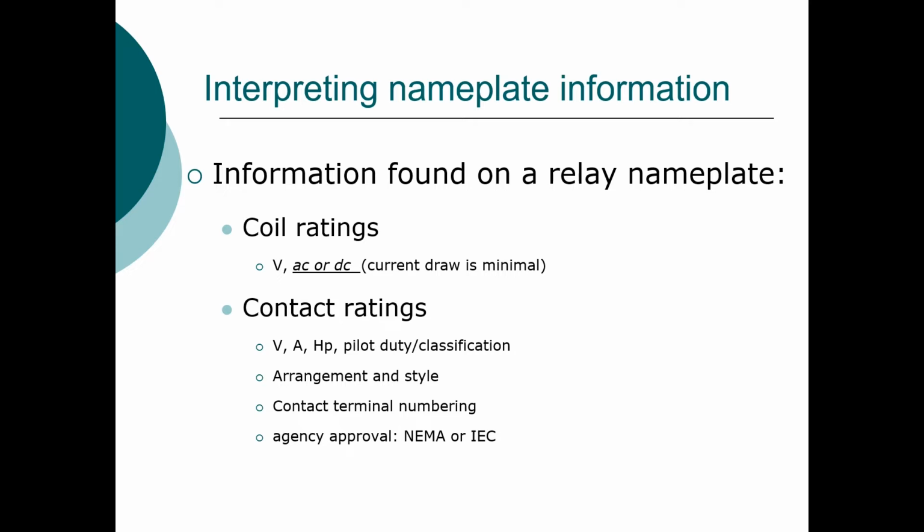The other thing I'm going to be looking for is any ratings on my contacts. And the contacts will have a lot more ratings associated with them, including voltage, amperage, horsepower, duty, the arrangement and the style, the contact terminal numbering, and whether or not it's a NEMA or an IEC design.